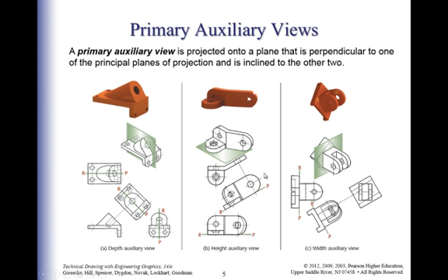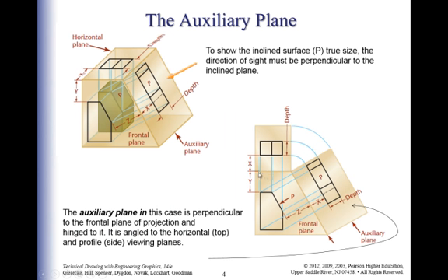Again, last week we talked about the auxiliary, the fold plane line. Right here it is, coming right through here, and this one we're showing it coming down right through here. Now remember something, we're looking at this. Remember how I told you top is the depth? Well, we're using this auxiliary. We're going to put this auxiliary view in place of the right side view. We're just transferring that depth. We just didn't transfer it all the way down to a right side.